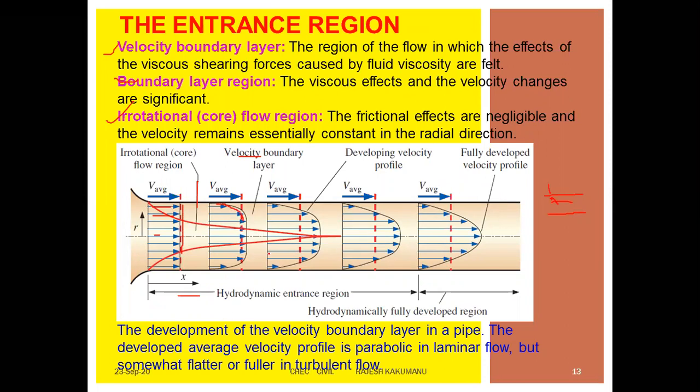Next, the third one. Here, the average flow of the water fluid is slowly converting into a bigger form of parabolic nature, right? Again, this one is making some extension, developing a velocity profile. So this shape slowly converts to the velocity profile, and the arrows slowly disappear at the boundaries and emerge forward through the center. So from this point to this point, it is the hydrodynamic entrance region.